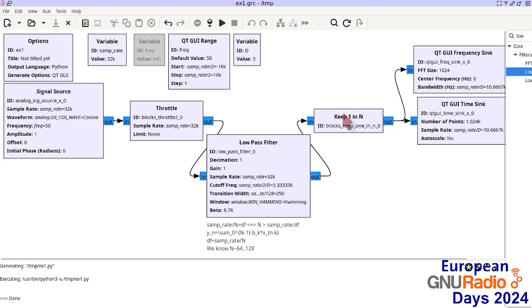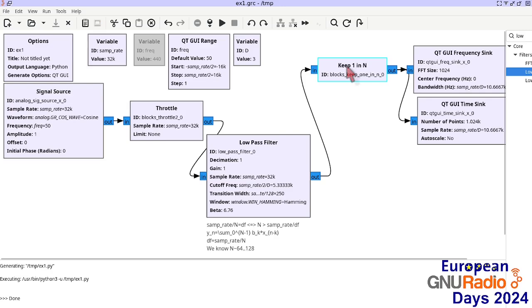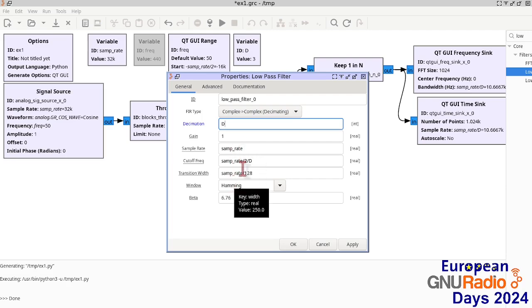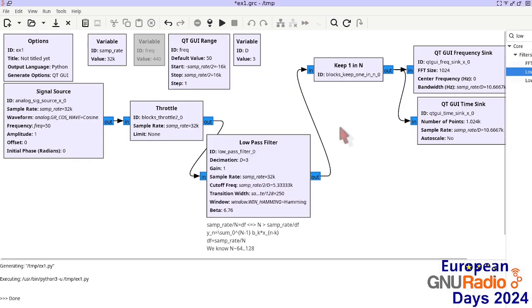Now, filtering and decimating are such common operations that usually you do not low-pass filter before decimating, but you actually decimate inside the filter. So be aware that here this decimation will take place after the low-pass filtering, after the weighted sum. Of course, if we were to do it before, then we would alias and there would be no way of removing this unwanted spectral component.